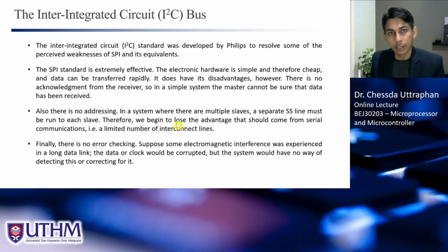So today we will look at another synchronous serial communication, which is the inter-integrated circuit, or I2C. This is another communication protocol that was developed by Philips, which today is NXP, the one that manufactures our microcontroller. The LPC1768 is developed by Philips also.